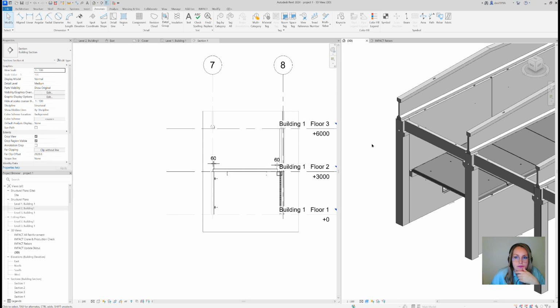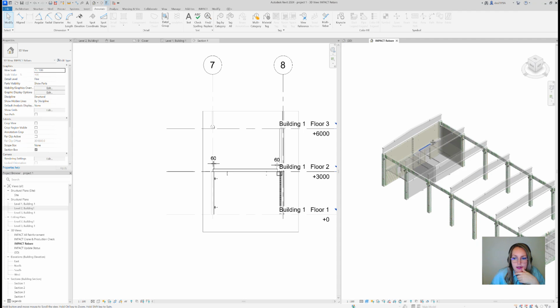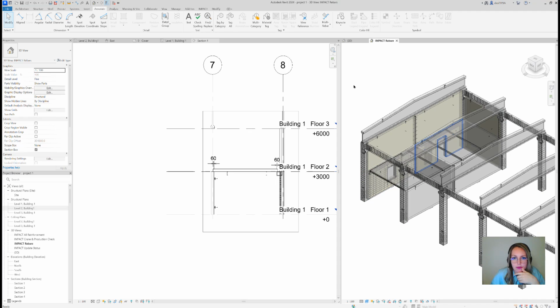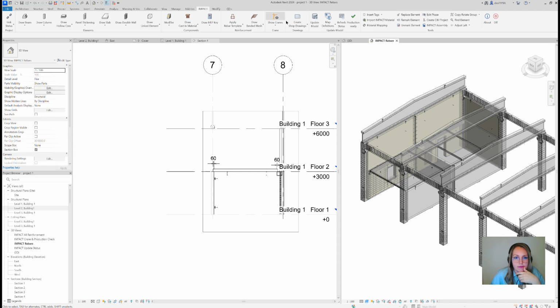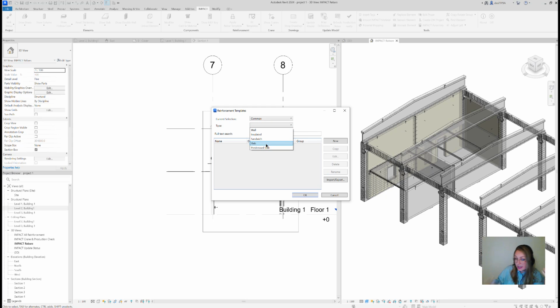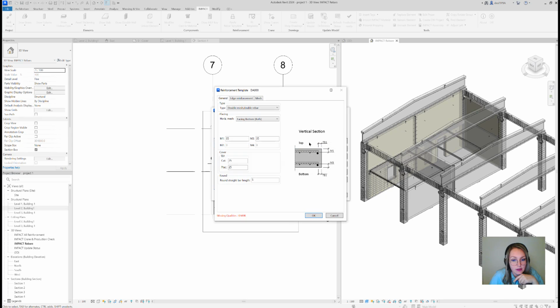Okay, if we go to the rebars, I think I can add some reinforcement templates to the slab. Reinforcement templates are not only for walls. If you go here, we have them for slabs, pre-stressed slabs, all types of walls. So slabs are also something we can do.